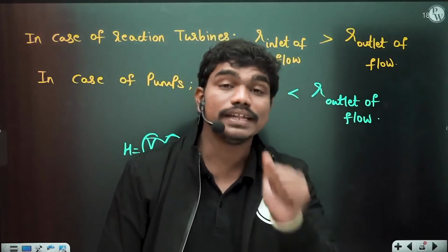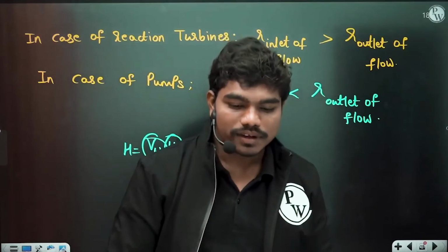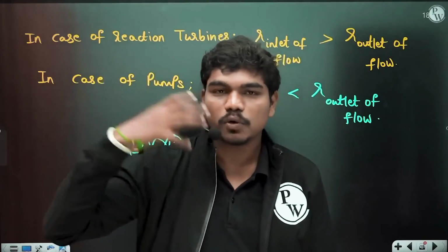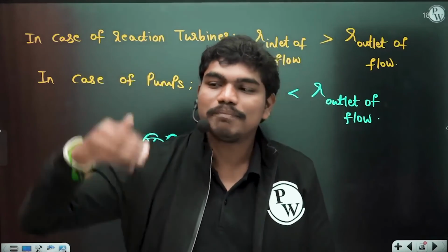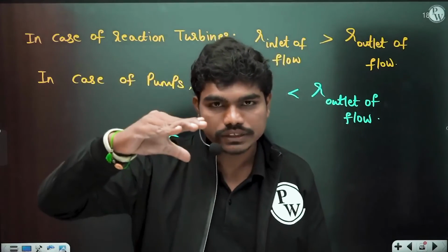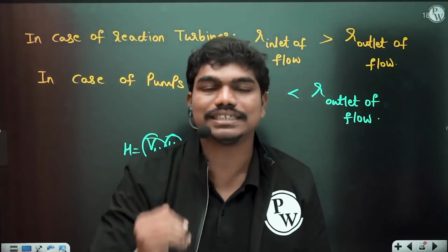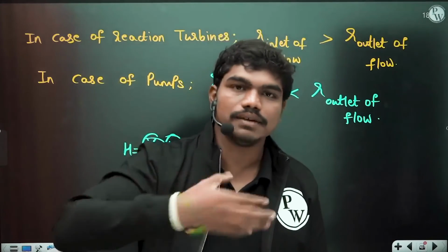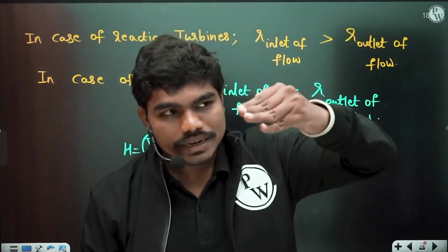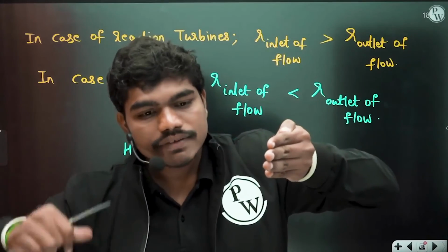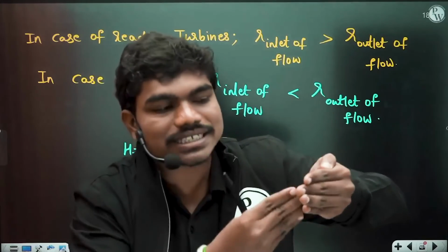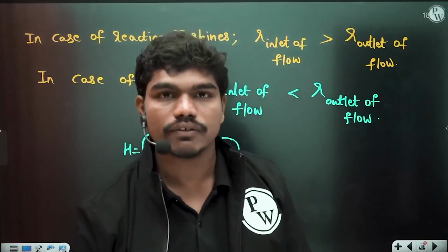Can you see this? Why is there a curvature? Ask yourself this question. Suppose you switch on a fan, you will feel some cool air onto you, correct? If you sit on the back side of the fan, will you get air? No, correct? Because the design or shape of the fan wing is such that whenever it rotates, it blows air in only one particular direction. The geometry of the blade is such that even though fluid is moving axially to the shaft, some component of tangential velocity will still exist and it will hit the blades. So that's very important.